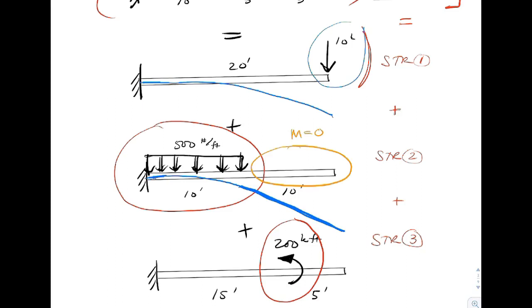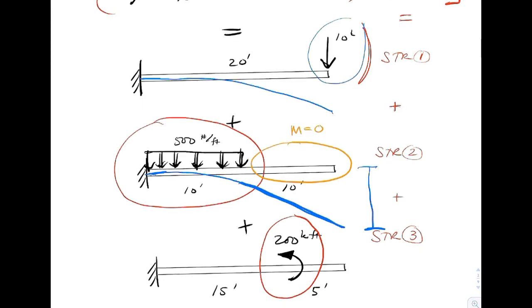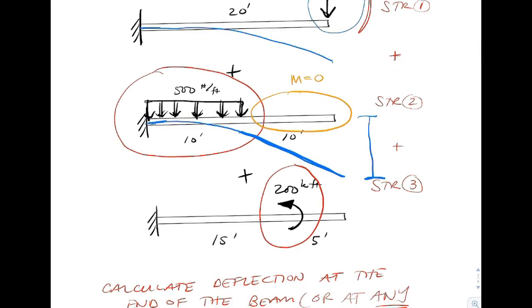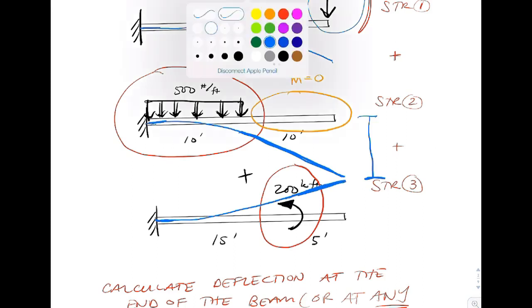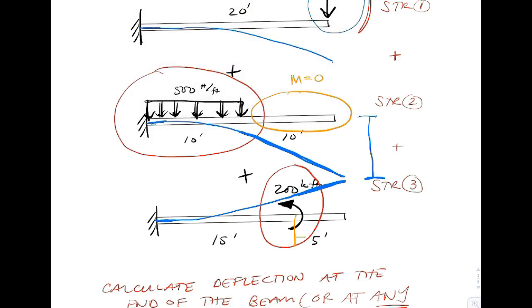So we're going to have a solution scheme, a superposition scheme, to help us solve for the deflection all the way out at the end of the beam. And same thing happens with an applied moment. If we draw the deflected shape, we get curvature or displacement up from positive curvature, and then we end up with a segment of the beam that has a straight line. And over those last 5 feet, if we cut that beam open, we find that it has 0 moment inside of it.